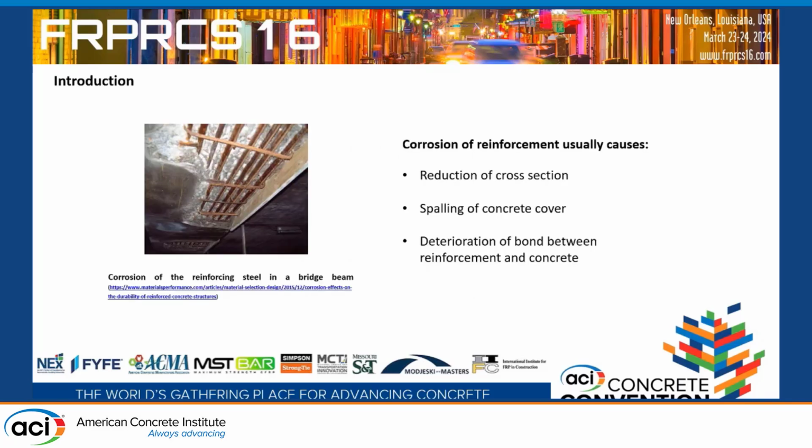So, corrosion is always a headache problem for engineers. Most engineers try their best to avoid the corrosion of reinforcement and find some ways to rehab the concrete beams with corrosion. Corrosion of reinforcement usually causes reduction of cross-section, spalling of concrete cover, and deterioration of bond between reinforcement and the concrete. A lot of researchers have done research with all of these factors, but nobody considers only one of these factors.